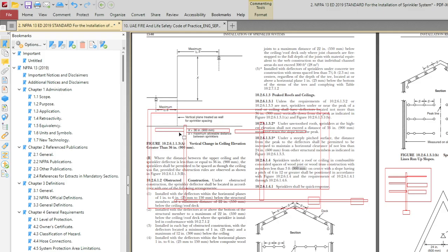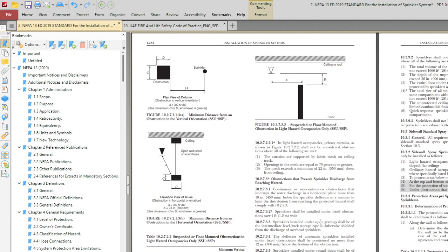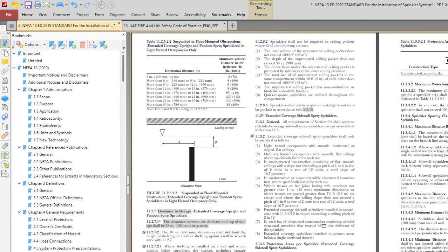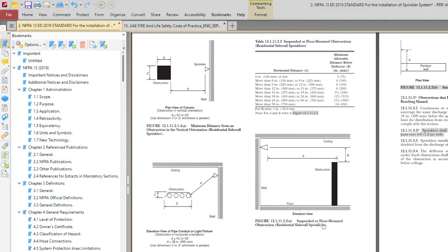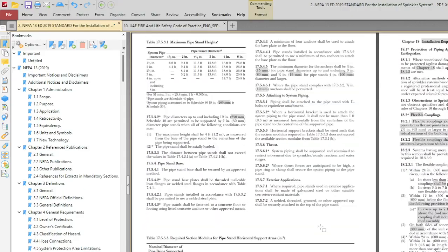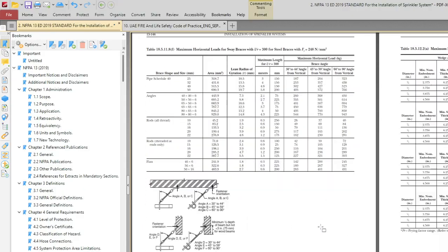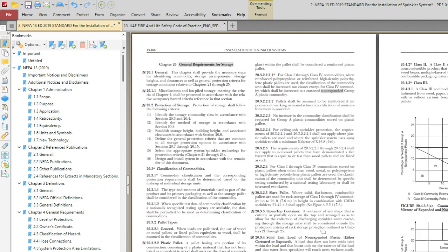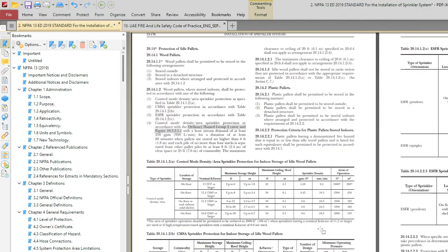Okay, now you can keep on doing the pipe sizing here. Now how will you do the pipe sizing? Remember we have one table here. You might have seen that it depends upon the number of sprinklers. From the UAE fire code, yeah, and in NFPA also it is there.